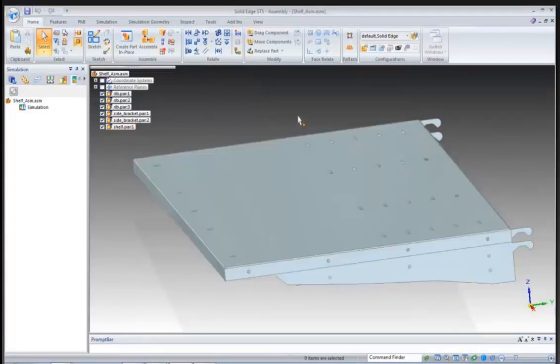And then for a surface element, it looks like a rectangle. In this case, it's a quad 4 if you're familiar with Nastran. And it has degrees of freedom that also include the rotational degrees of freedom. So it can rotate around the x, rotate around the y, rotate around the z.